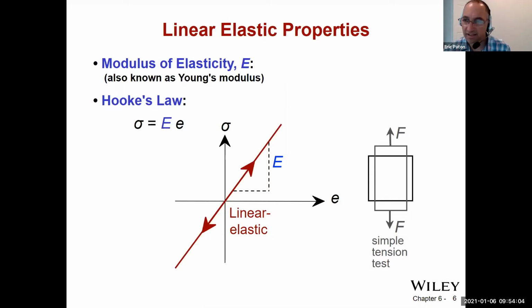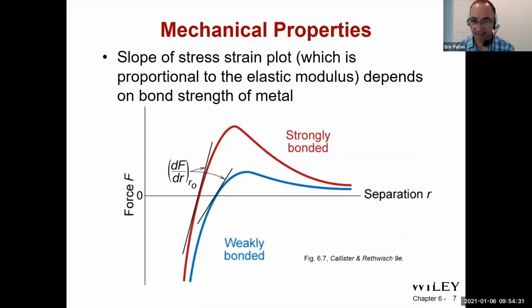But wood, I guess it depends on the type of wood. But yeah, it's possible that wood can be pretty stiff, especially since you have all those fibers, and if they're in line with the flex direction. Good. So these all have very stiff bonds, and they all have very high elastic modulus. And that just gets into this point here, where it really is a strong bonding or a weak bonding, not the ultimate strength of those bonds, but the stiffness of those bonds. Okay. And so the red line would be a very stiff material like carbon fiber, and the blue line would be one that has a low elastic modulus.